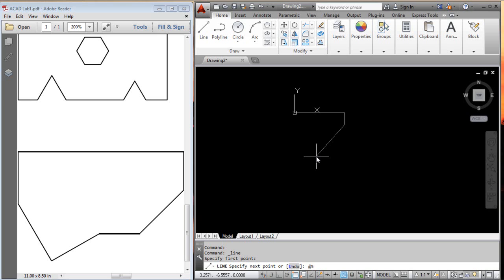I'm going to make up a distance of 5. For the angle, simply hold Shift on your keyboard and hit the comma, which is the same key you use to separate X and Y. Now we're separating distance and angle. The angle on this calls out 45 degrees relative to the horizontal, and the horizontal axis is actually 0, or over to the left side 180. So relative to the 0, it would be 45.